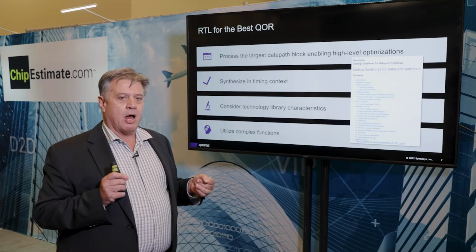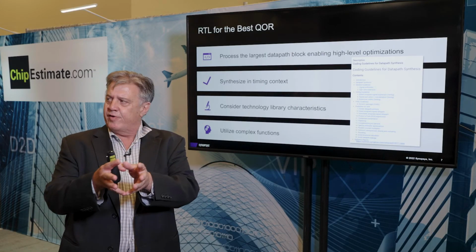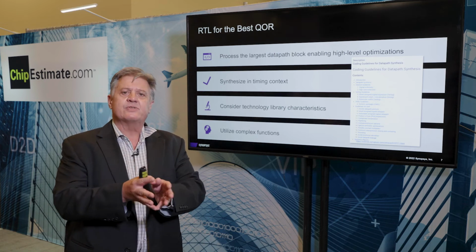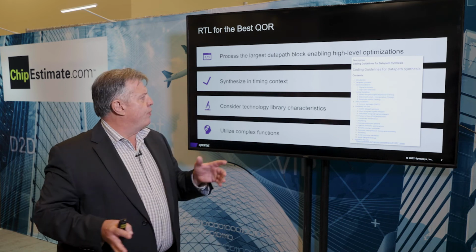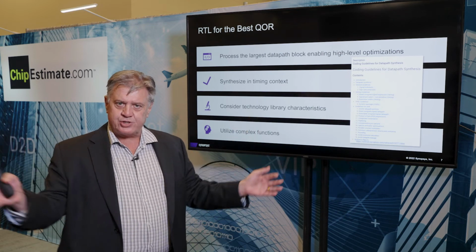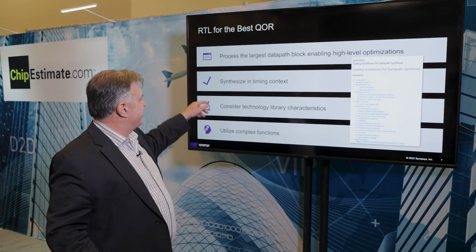Look for the largest block. I've seen many designs that are over-constrained. People put very tight constraints on their block. It's really not what we want. Let the synthesis tool do optimization, eliminate the gates, improve the latency.